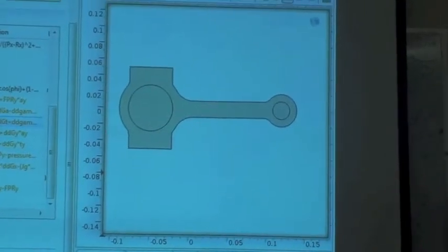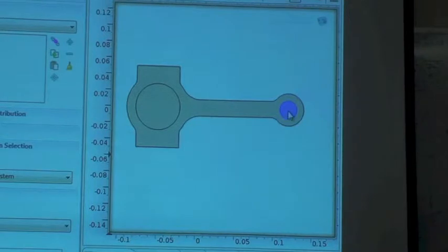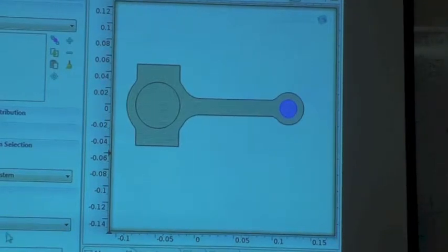Then you want to put an axial load on this. Because this is fixed, but this still has axial load caused by the piston pushing down on it. So this is just the force PRA, which you did in the load analysis. Again, it calculates it. And this is a total force, though, it's not force per area. So if you just set it up like this with these constraints, you should be good. Everything else is defined, material, definition.